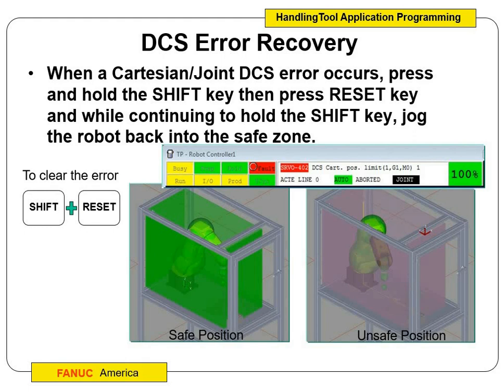When you see that, that means you've moved the robot outside the working envelope. The only way for you to get the robot back inside is to make sure that you are in joint. Okay, first of all, you have to hit coordinate and be in joint, and then you have to hit shift and reset, clear the error. Make sure when you do all this that your hand is in the center position on the teach pendant, and you have to jog in joint back into the working envelope. That's the only way that it'll let you do that.